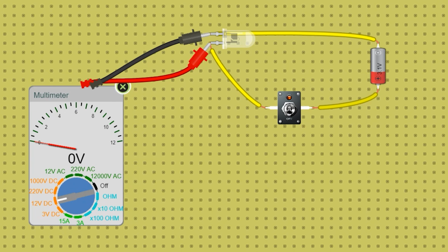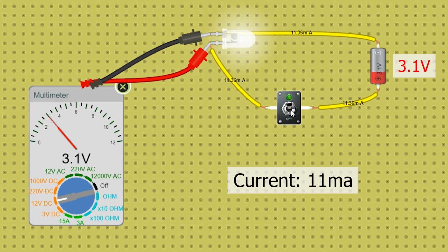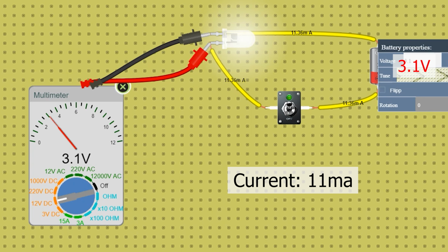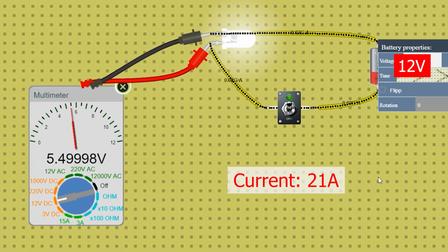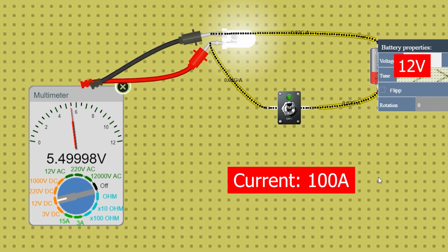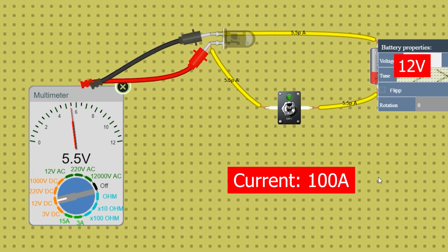Now, we've established that voltage drop across the LED's terminals is constant. So, the LED acts as a kind of regulator that strives to keep voltage across its terminals unchanged. If you attempt to raise the voltage, the LED will react by increasing current. This will prevent voltage rise. However, if you insist and apply, say, 12 volts to LED's terminals, the current will increase manifold, which will result in your LED burning out instantly.